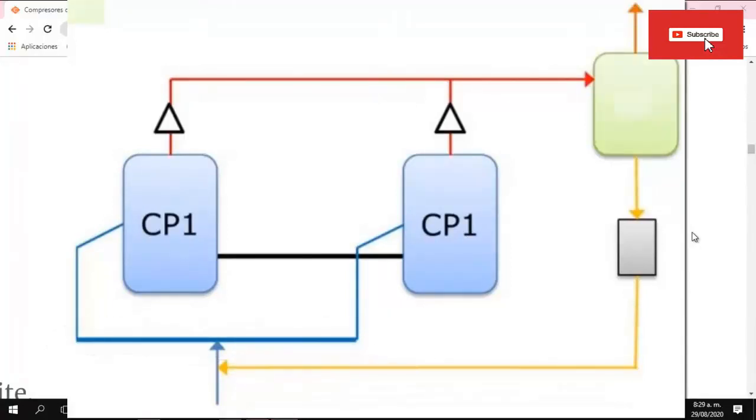8. When only one compressor is running, the oil level of both compressors is within the glass. 9. The oil level of a running compressor is higher than the standby compressor. This is due to a lower pressure inside the running compressor. 10. When both compressors are running, the oil level is high and the pressure is balanced, and consequently the oil balance is good. 11. The cost is relatively low.